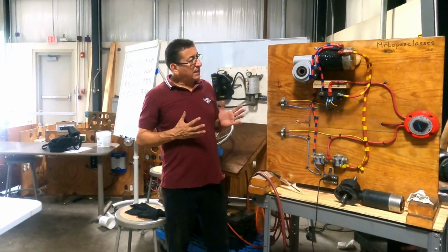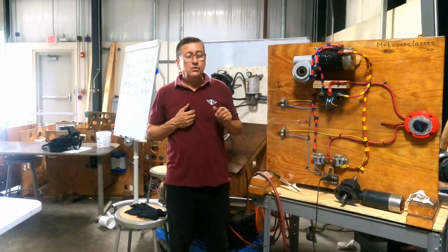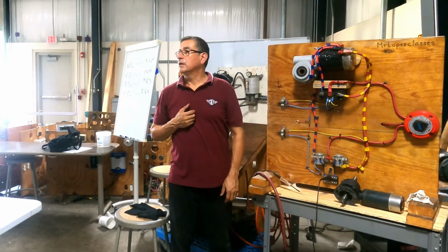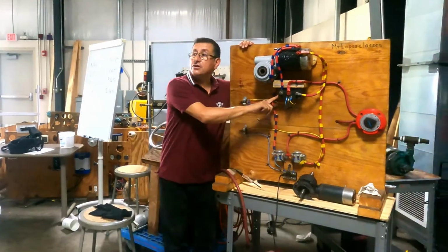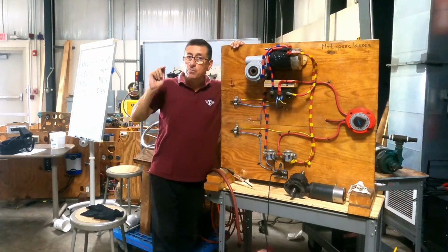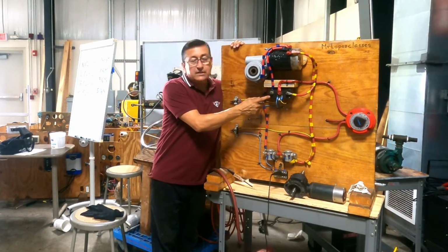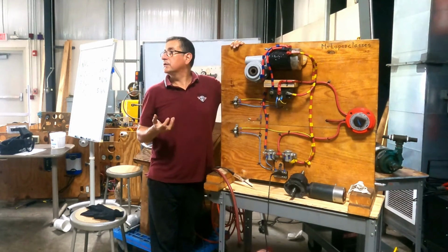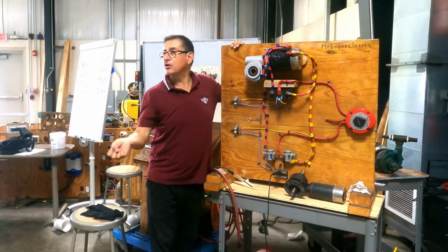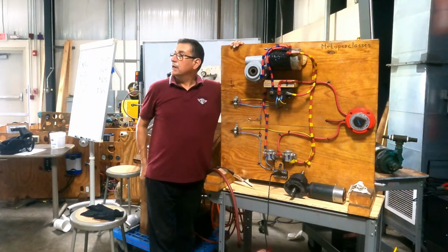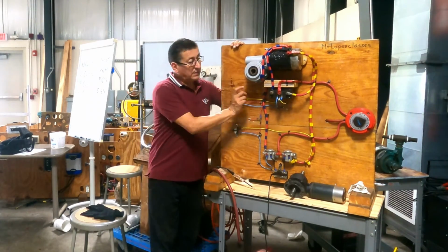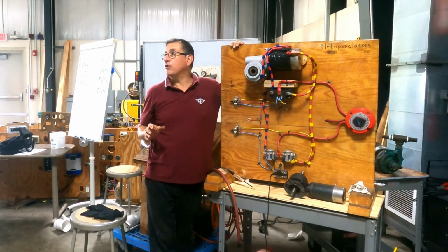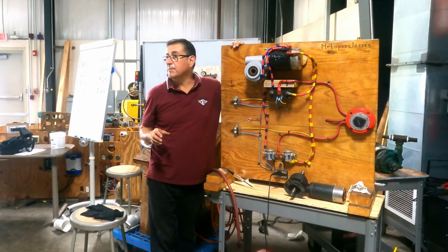Okay. This is a great opportunity to demonstrate to the customer that the solenoid control box is damaged. This element is expensive. It is commonly damaged because where is this element located? In the windlass compartment, and a lot of water splashes over there and it is corroded. This is a common situation. That solenoid control box is not working. Okay. How can you fix the situation in the middle of the ocean?